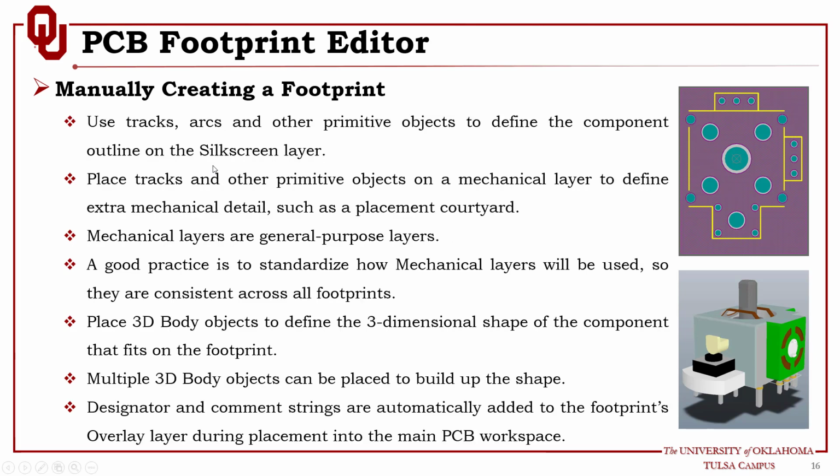There are multiple ways to do that. We can manually create a footprint, or we can use the IPC footprint wizard, or we can use the footprint wizard or the batch generator. And there are a lot of things to cover in the footprint. It's even more than what we covered in the schematic.